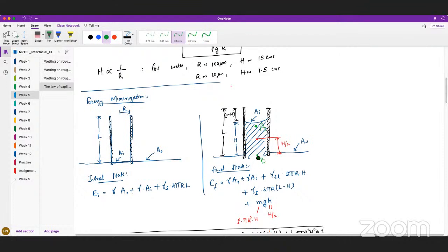And actually, sir, A is moving up with a higher velocity. If A is a point at the center, then the velocity is also higher, because that profile is then parabolic. So it would be 3/2, 1.5 times more velocity at A.